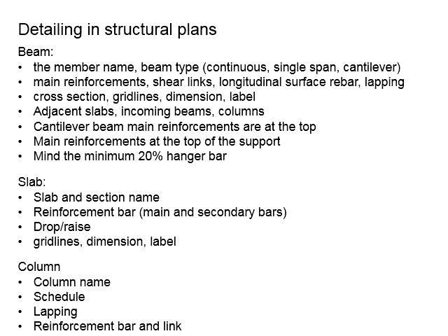The detailing of the slabs can be presented through the cut sections of the slab in reference to the structural key plan, and you need to provide adequate cut sections to demonstrate to the contractor the layout of the reinforcement bar that differentiates which is the main and which is the secondary reinforcement bar.